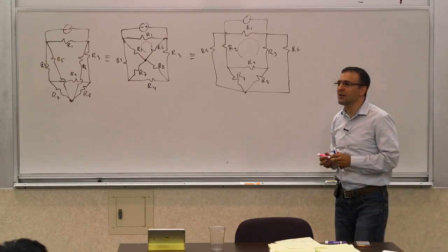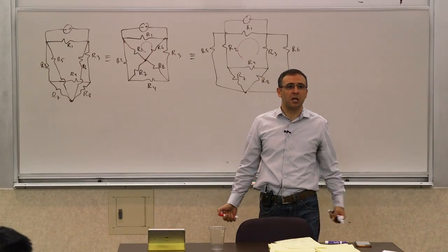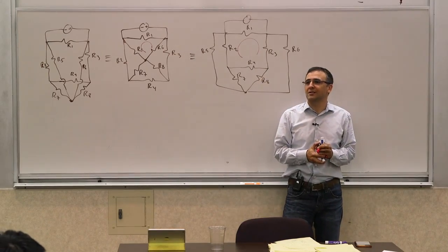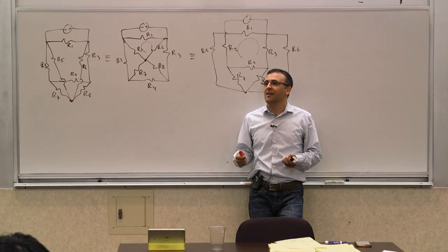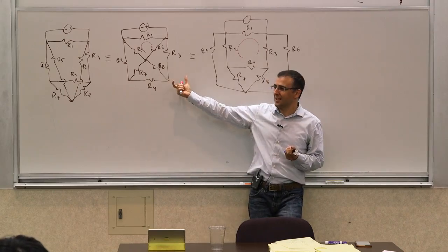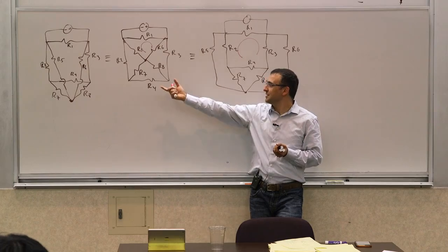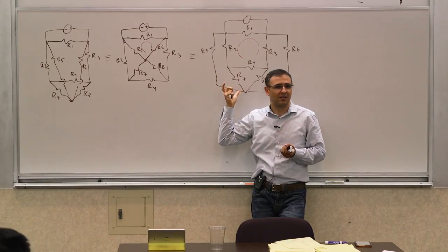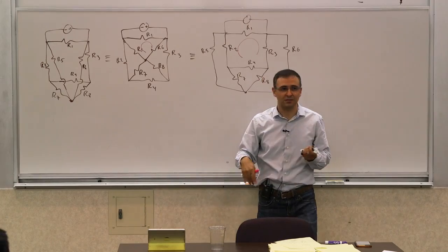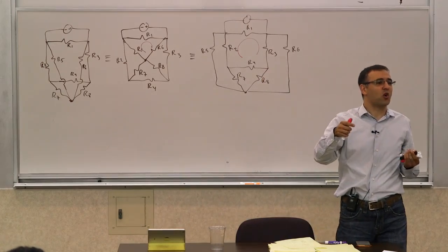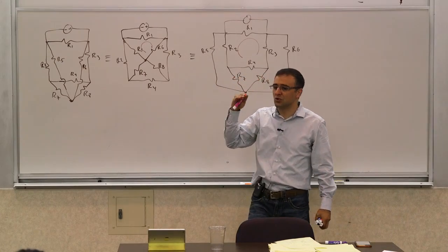Now, this brings us to the concept of topology. We refer to circuit topologies. So you may hear topology constantly, if you're in circuit design, say, use this topology or that topology, right? That's why they refer to it as topology, because it's not the exact position, it's the way they're connected that matters. So topologically, these three are the same. And that's why you constantly hear people refer to this circuit topology, that circuit topology, et cetera, because it's the way it's drawn. And that's important because a lot of the concept and intuition comes from the way we draw things.